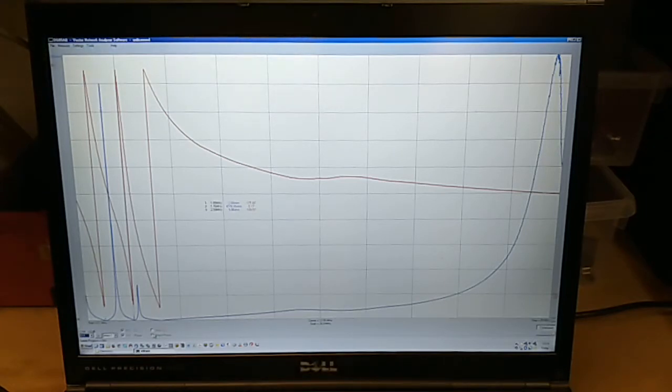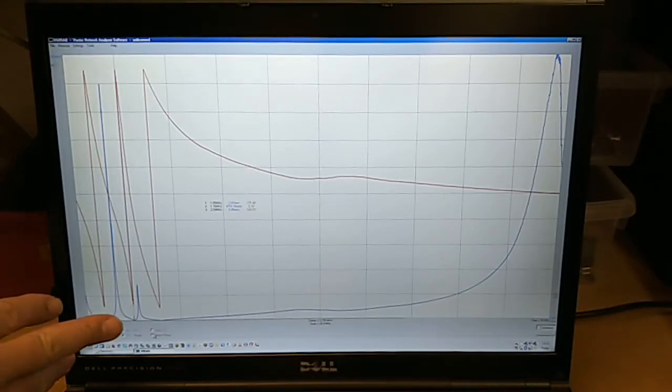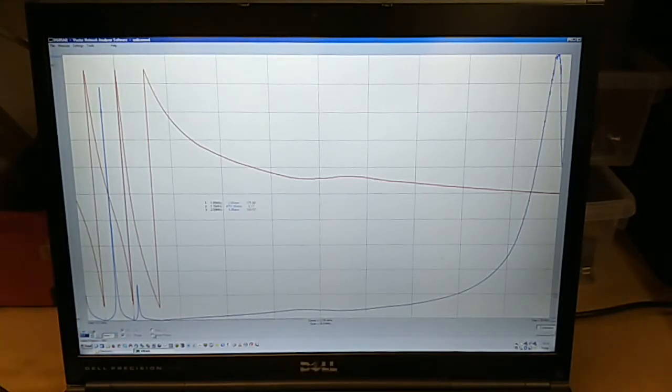So in other words, that serial point represents, which is largely defined by the transmitter, those oscillating currents, is where the ring down is taking place. So in other words, that secondary is ringing down and it's ringing down predominantly at that frequency, and that's what's being measured predominantly in the primary circuit.